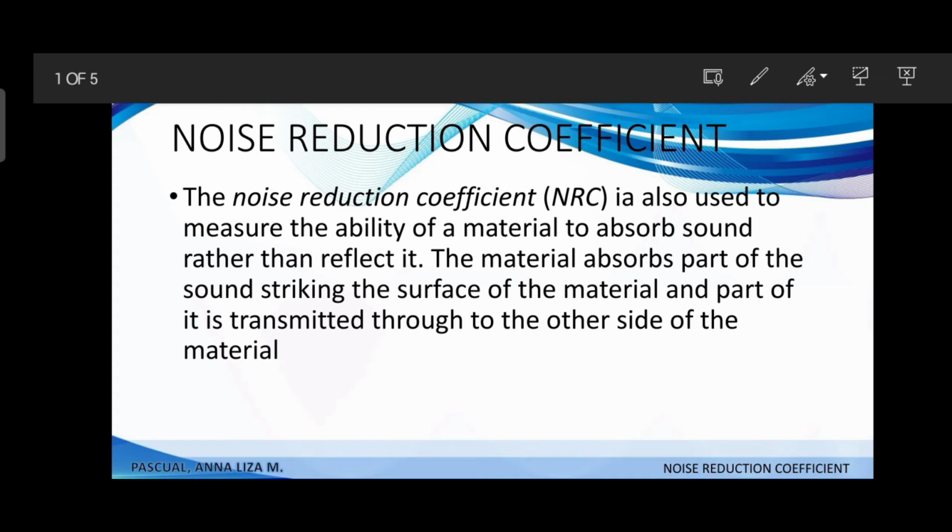NRCs for selected materials and finishes are provided in Table 23.12. The recommended NRC for surfaces in most rooms is between 0.6 and 0.75. Special consideration should be given to computer and accounting rooms, classroom, kitchens, and any room where excessive noise is generated.